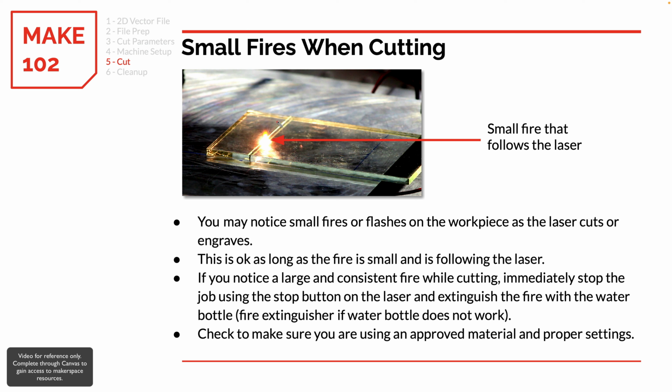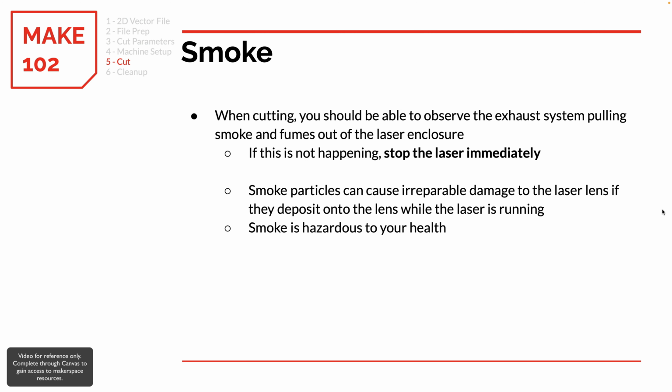You can stop the job, open the lid, and try to spray to put those fires out. You should also verify that there is no smoke buildup in the build chamber. Smoke should be actively being exhausted from the chamber. If that's not happening, stop the cut immediately.